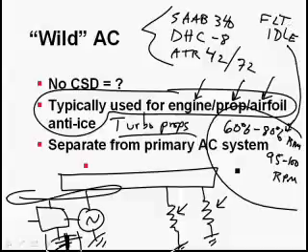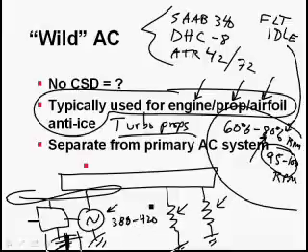60 to 80% would be flight idle. So even though you pull the power lever back to 80%, it's still going to work pretty good, and you're hardly ever going to pull the RPMs back. You just pull the power lever back, and the RPMs are going to stay at 95 to 100%, even at lower power settings. So the RPMs don't change very much, and the AC generator stays at a reasonable RPM. It definitely does vary. You do not get 400 hertz out of it. You might get like 380 to 420 hertz out of it, say at 100% RPM, and say at like 70% RPM.